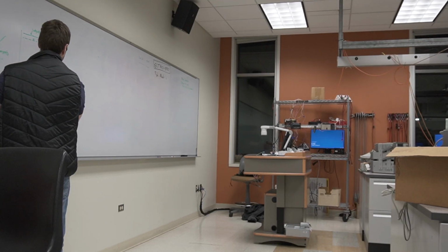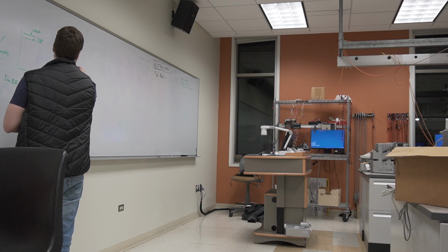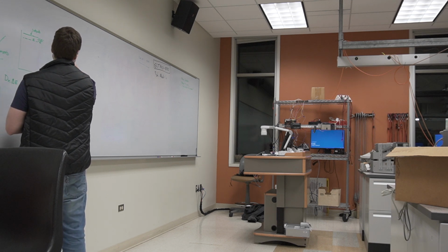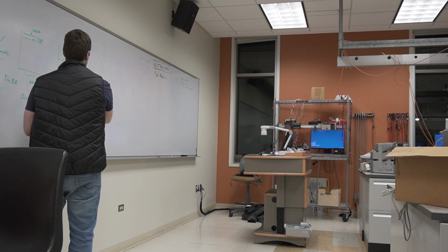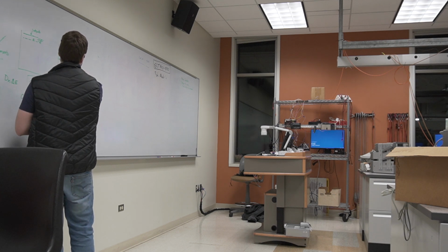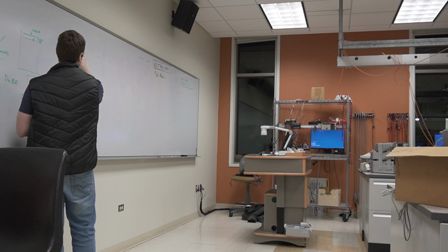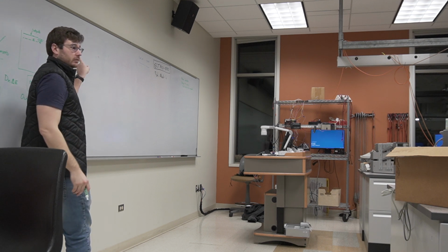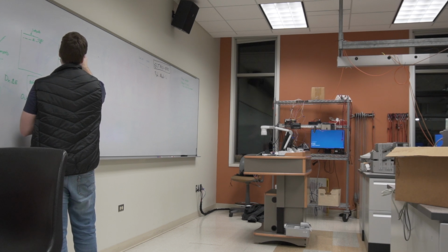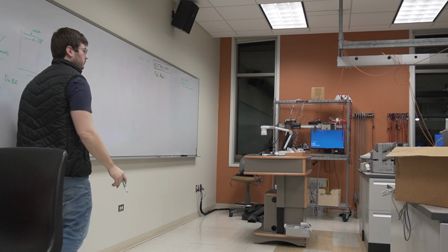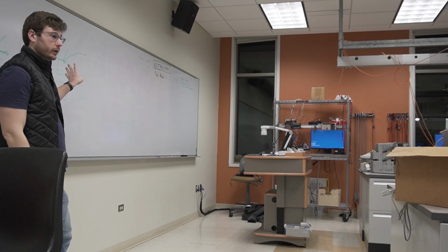But D responds accordingly. If we had a line like this and super suddenly we're off the charts, a PI controller would not fare very well against this sudden change. It might go like this in response, a huge long curve, and our process variable might never recover because we don't respond quickly enough.